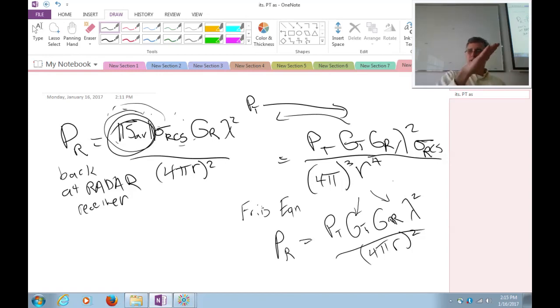I mean, I can make approximations, say, well, most of the users are on the horizon, so maybe I can get gain that way. But especially at the user terminal, if I'm receiving a signal, I don't know where the signal's coming from. If it's a mobile phone, I could be here, I could be here, I could be looking up, I could be turning this way. I have no idea a priori where the signal is coming from. So by necessity, any mobile phone antenna is going to have a really low gain, usually no better than 1 or 0 dBi. And the transmitter gain is not going to be much better in low frequency transmission applications anyway,